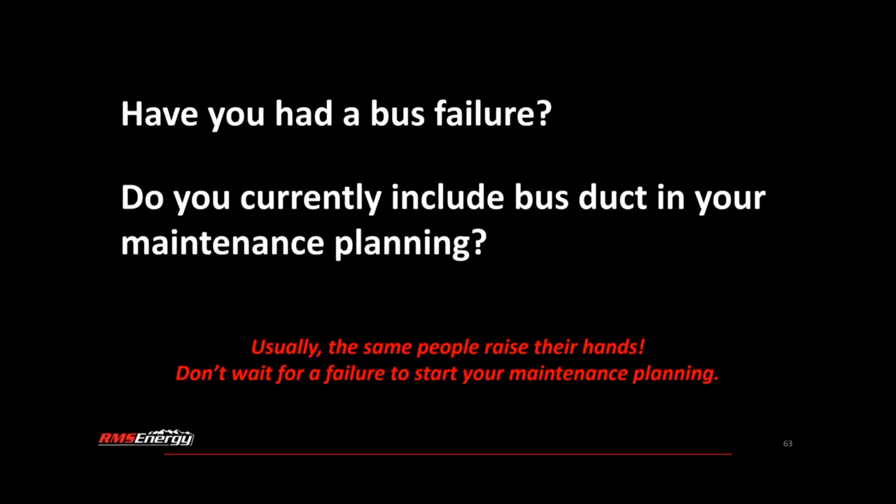Okay, Brian, what determines voltage levels applied for high pot testing isophase bus bars? So high pot testing voltage is going to be determined by the BIL rating of your bus, which you'd have to look at your rating nameplate or your drawings to determine what that is. But all manufacturers are going to specify that in their design data.